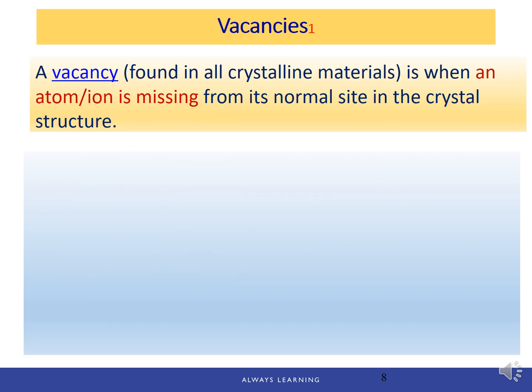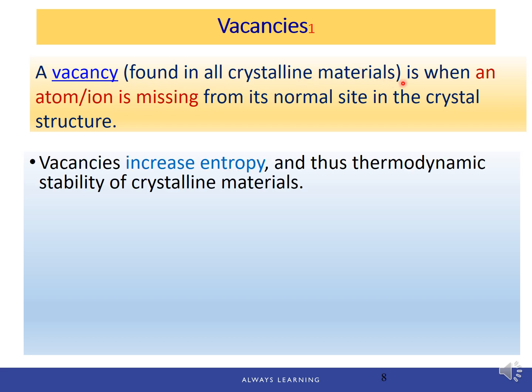A vacancy is when an atom or ion is missing from its normal site in the crystal structure. It is impossible to find a material without vacancies, so they can be found in all crystalline materials. Vacancies increase entropy and thus increase the thermodynamic stability of crystalline structures.